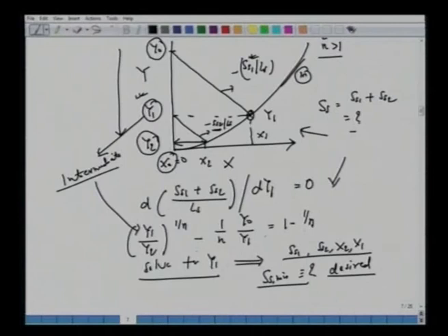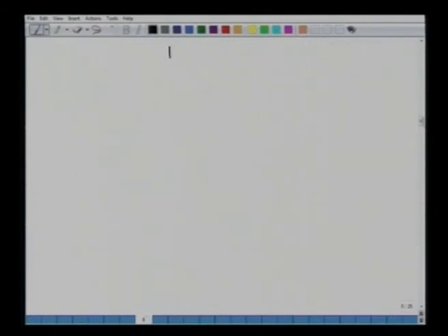And actually when you solve this, of course it looks like there's an iteration here. Y0 is fixed, Y2 is here, so one is to solve this by trial and error or some numerical technique to obtain these values of Y1. Then you can go back and put the equation for the first stage and the second stage to obtain the other quantities.